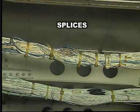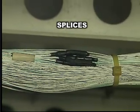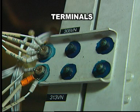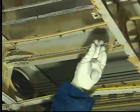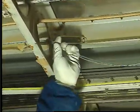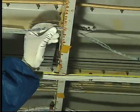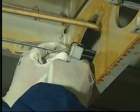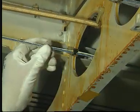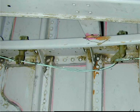Splicers, grounding points and terminals must be thoroughly checked for the insulation, the tongue, the barrel and the retaining sleeve damage, cuts, burns, etc. For the bundles, do a check of the sagging phenomenon. In this case, do a check upstream and downstream of the sagging to find the location where there is too much tension or reduced length. Redistribute the sagged length. Install new attachments, cable ties in this example, and check by pulling lightly on the bundle to make sure that it is correctly attached.